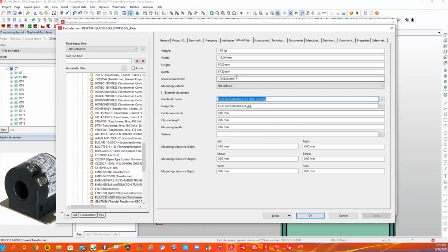We do have an ePlan data portal standard that just came out. It's a new standard that all manufacturers have to abide by, and that's starting to trickle down. So a lot of the data requirements have to now be enforced: 3D information with height, depth, mounting clearance for heat dissipation zones and whatnot.